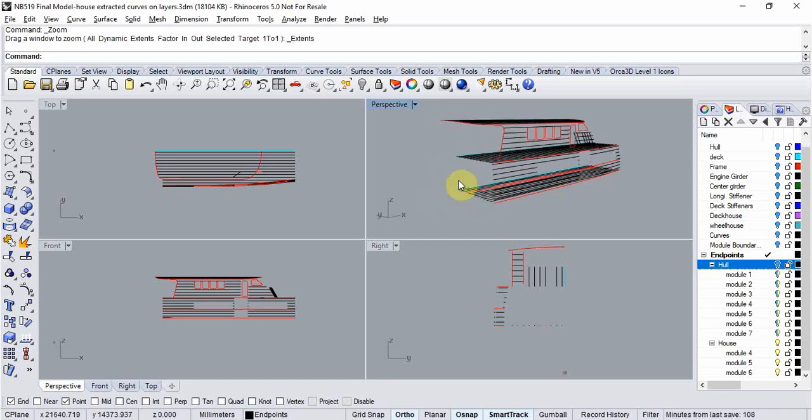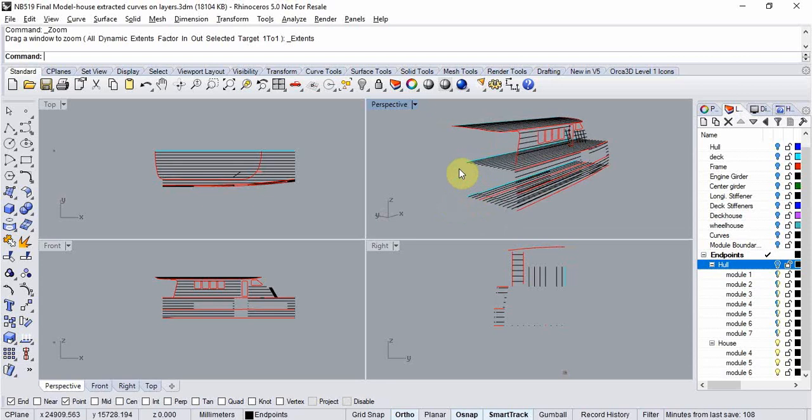The remaining curves on the interior of the deck are there for reference, so that when we later build our transverse bulkhead, we can be sure that the nodes at the bottom of the bulkhead will tie in with the structure for the hull.